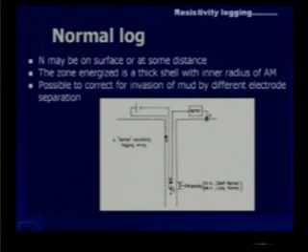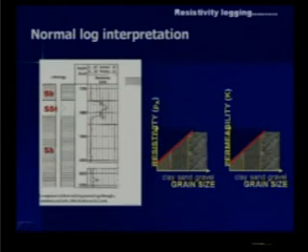One current electrode is kept at the bottommost point of the borehole, another current electrode is at the top through which we are energizing, and of the 2 potential electrodes, one is kept within the borehole, another on the top of the surface, through which we are measuring the potential. This is one kind of arrangement.